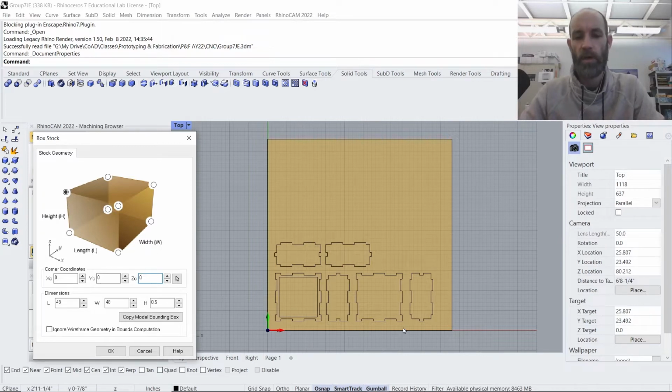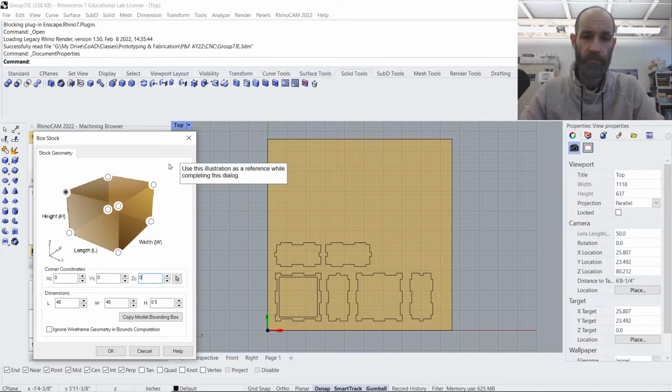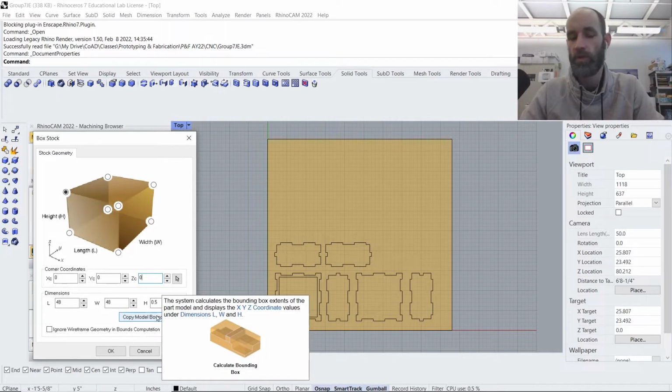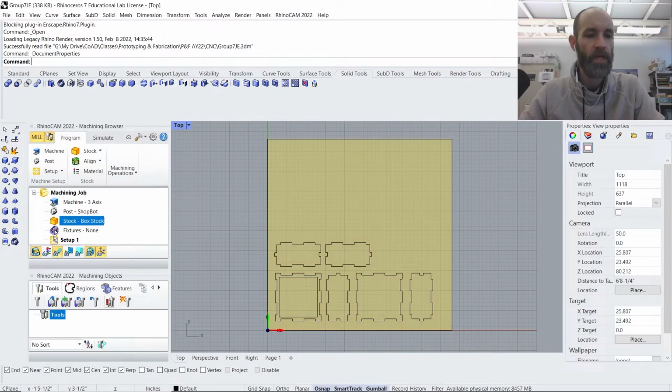And anytime we're defining values in the software which have a depth, we're going to be cutting into the negative Z dimension. And remember, we set that tolerance for the machine, the maximum depth at 0.05 here specified in the material. So that will ensure that we're not going to cut into our table. There are various ways we could set this up. We're just using this as an example today, and how we will often do it in our shop. So I'm going to confirm these choices by selecting OK.